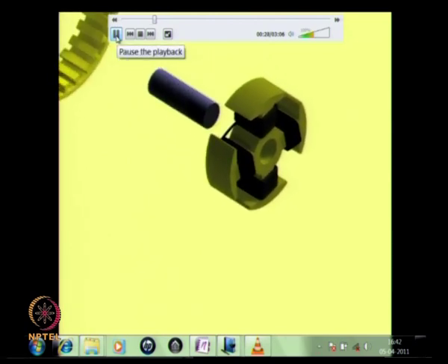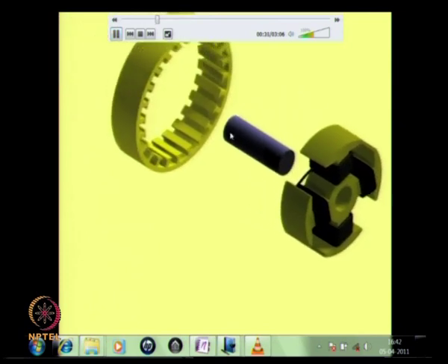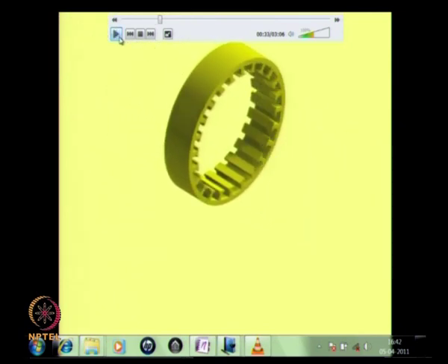This is how this is going to look, and here you have the shaft and the stator coming here. This stator has several slots, as you can see. In spite of these slots, we have said at the outset that we are neglecting the slotting effects in the stator. So, what we are assuming is that the inner surface of the stator is really smooth all along, and we have certain armature that is wound in these slots. So, let us continue with the animation.